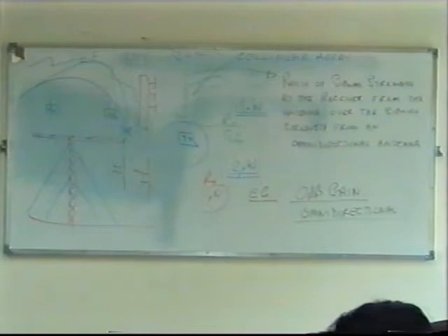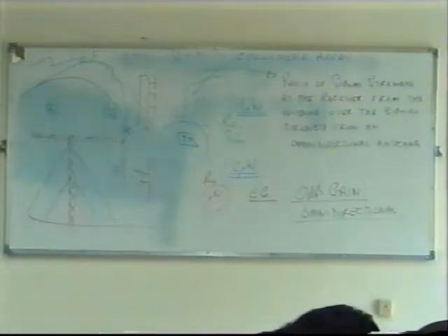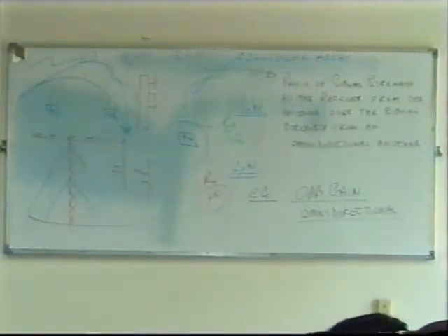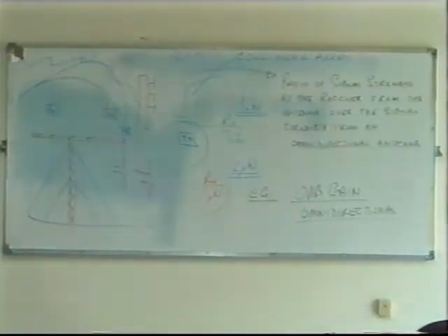So in any antenna, if you use more than one dipole, you are directing the wave. Yes, what you're saying is in any antenna, if you're using more than one dipole as part of that antenna, it's directional, and it's going to have a gain greater than one, either active or passive. In this case, it is passive. Yes, even active. Now that brings another question. Say you have a dipole, which is supposed to be omnidirectional, okay?